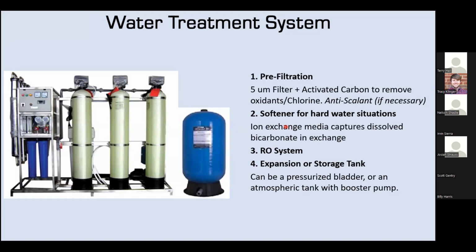RO systems work really well for humidifiers, and the system itself contains several components. You have the RO system, but generally they require softened water pretreatment. Just an important consideration: we do size RO systems for our humidifiers. The tank is a very important part to consider, because we want to make sure we refill our humidifiers fast so they can keep producing steam. So tank sizing is crucial, and something I've seen where the RO is sized for the steam output, but the tank can't refill the humidifier, and then you go into alarms and downtime.